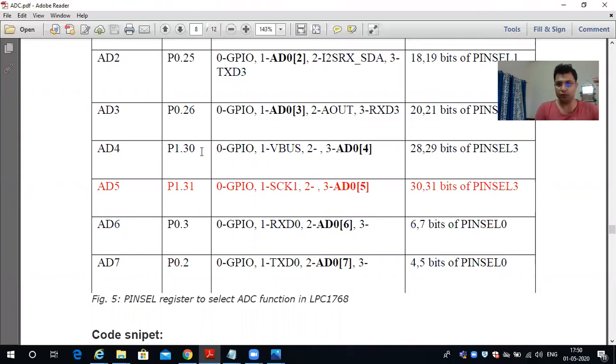Because 8 inputs are possible, at a time in parallel, 8 analog inputs can be fed into the 8 channels, but there is only one approximation register. So even when we have to convert all the fed-in analog signals in parallel, that will happen in a round robin way.